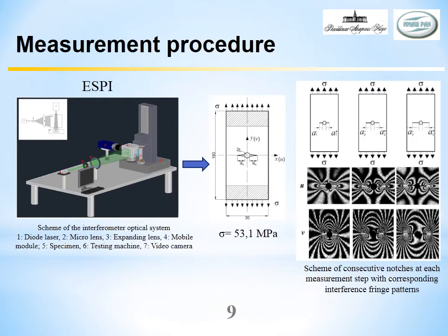After preliminary low cycle fatigue loading, consecutive narrow notches emanating from the hole are performed under the constant external load. For each specimen, all experimentally obtained parameters correspond to constant remote tensile stress 53 MPa. Step-by-step procedure of increasing notch length is performed by narrow saw of width 0.017 mm.